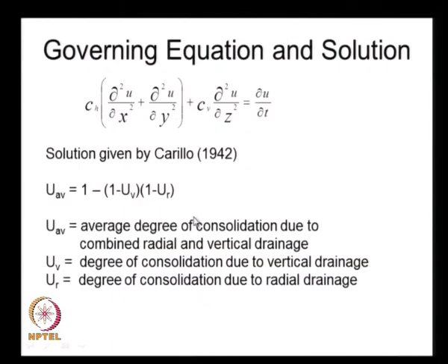The design of the sand drains is based on certain principles, and the governing equation is the 3-dimensional consolidation equation, where u is the pore pressure, x and y are the horizontal dimensions, z is the vertical dimension, Ch is the coefficient of consolidation in the horizontal direction, Cv is the coefficient of consolidation in the vertical direction, and t is the time.